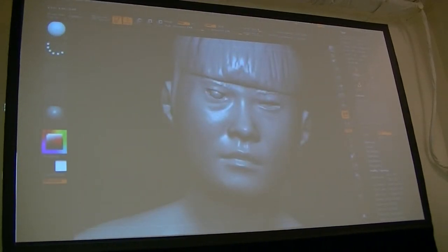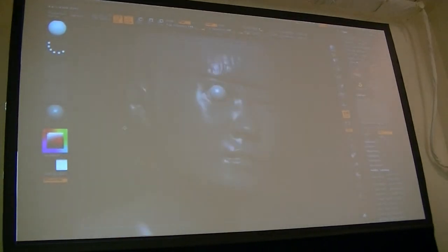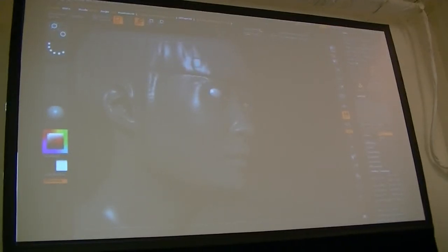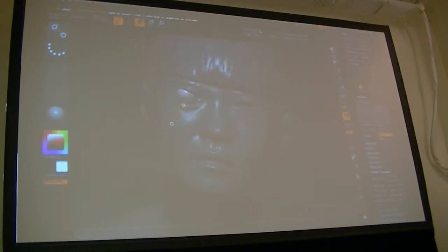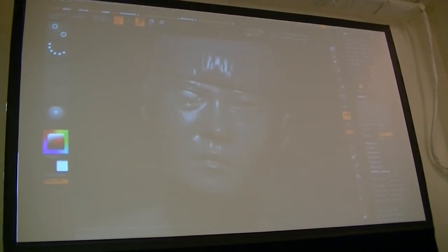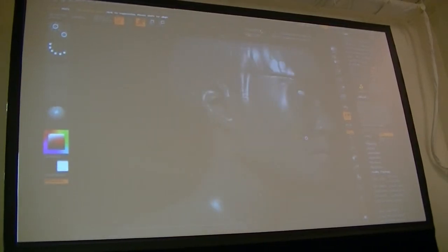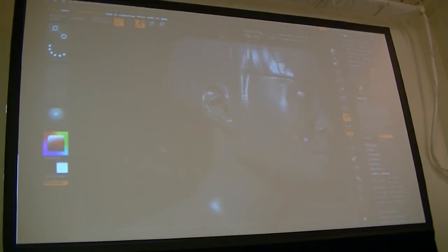And then I'm going to choose a sphere and just drag that out. This is insert. I'm using the insert sphere option. So what I do is click sphere and then just click and drag it out. What I try to do is get the first eye as good as I can get it, and then I'll just do duplicate and mirror.